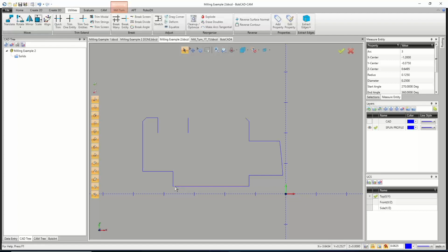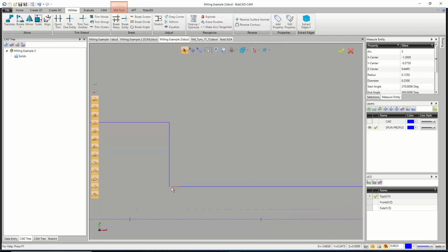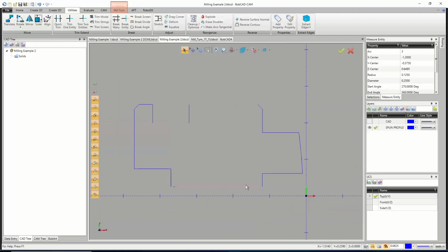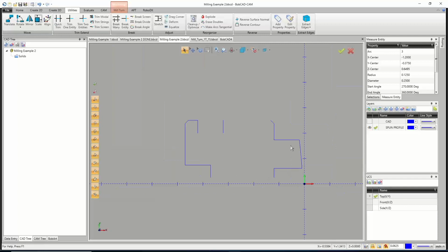And this bottom one's broken, which again I don't really need, but I'll go ahead and get rid of it and redraw it. And that's got a tiny little entity on the end of it that we got to make sure to get rid of. Otherwise, we'll have little duplicate overlaps. So there it is. Anything else that's broken, usually the breaks are going to happen along the x-axis, parallel to your x-axis of your CAD window or your z-axis of the job.